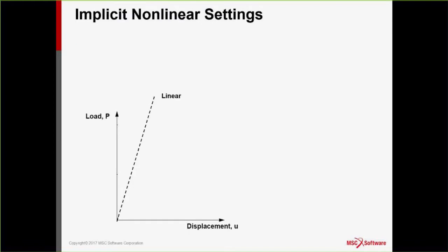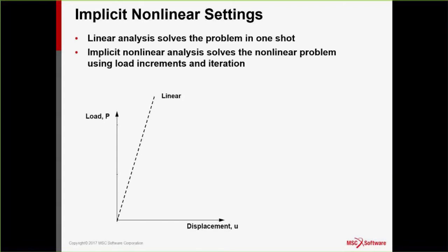Okay, the second thing, let's look at the smart settings I talked about. But first, let's look at how we solve a nonlinear problem. When we solve a linear problem, if I did a load deflection curve, it's pretty boring, right? It's just single stiffness. So it's a straight line. Now, if you want to solve a nonlinear problem like this, the load deflection curve shown here is a curve. I cannot solve that in one shot.